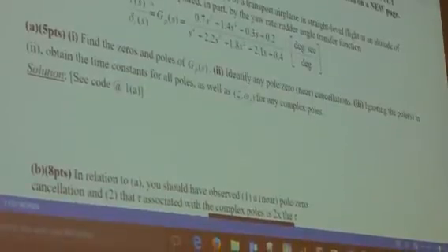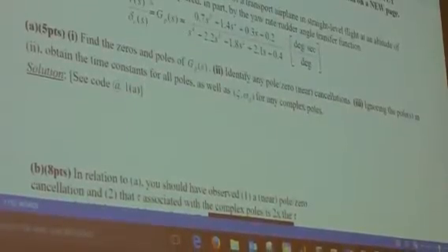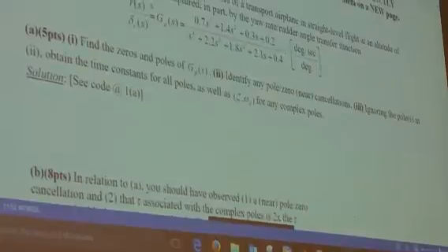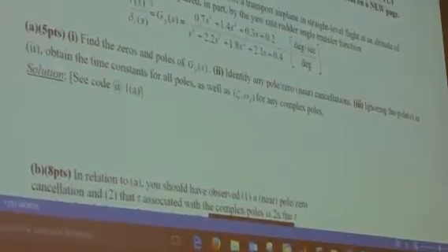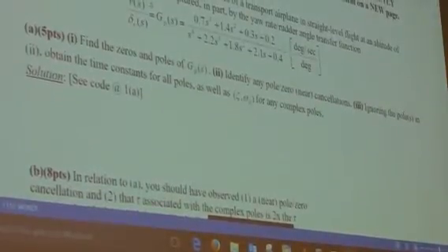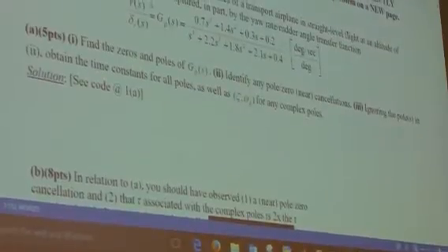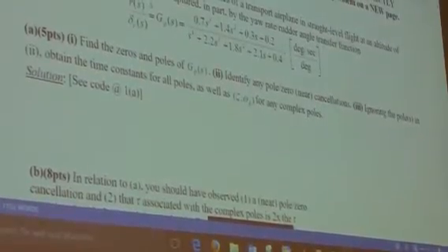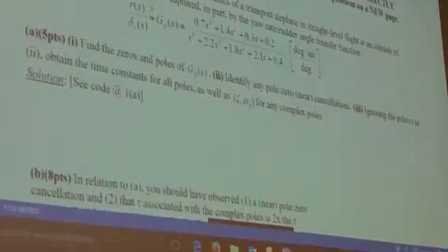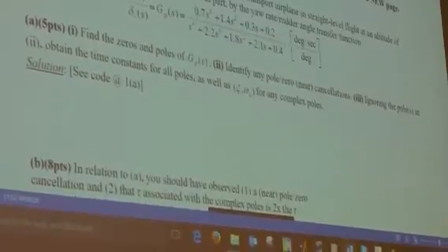All right, so there's the yaw rate, and the rudder is an angle. It's not a velocity. You guys know this better than I do, probably. So there's the transfer function. The units are degrees per second. That's the output, because it's a rate of yaw. The input is the rudder angle, theta. So the units are degrees per second divided by seconds. Okay?